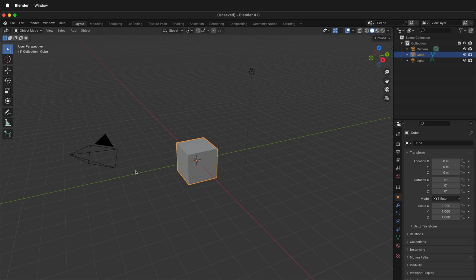One of the most difficult things to realize about Blender and many 3D modeling programs is when you try to click on things, sometimes they don't move like you would expect them to do. So I can click with my left mouse button and nothing happens. I can even highlight and marquee and no movement happens. So we'll talk about how to move things with the icons over here on the left. But before you can even move, it's important to be able to navigate 3D space.